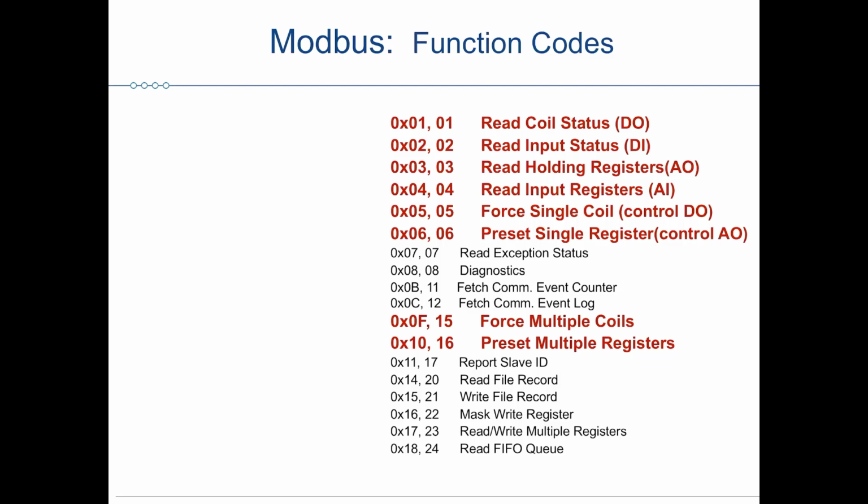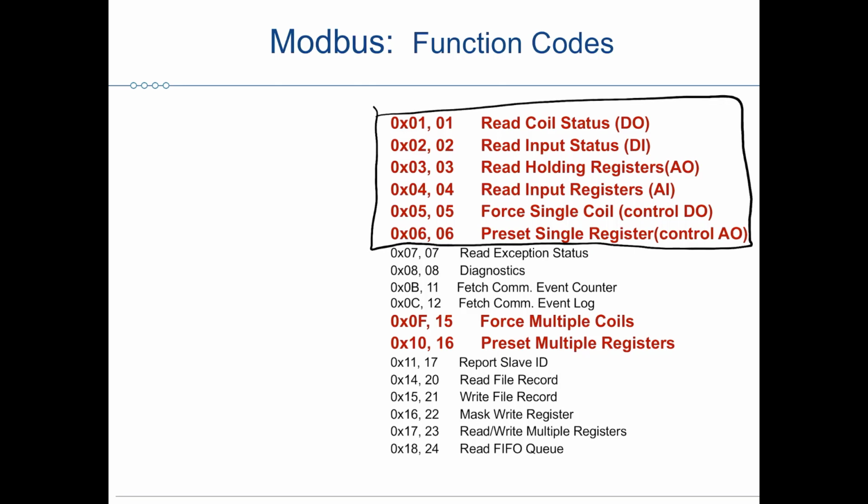When we look at these function codes, these are the ones you're going to find on your Modbus handout. They're the most used and popular of the function codes, but it's good to know there are other function codes available, and there's also user-defined function codes where, because it's open source, you can make up your own function code and have it, say, read a video file or a sound bite or some other data type that doesn't fall within these categories.